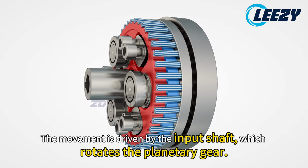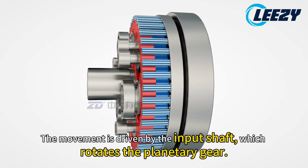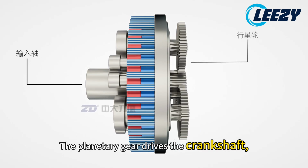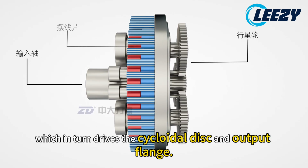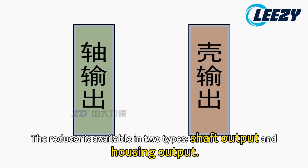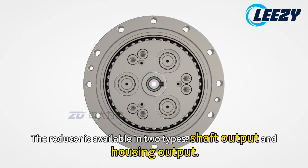The movement is driven by the input shaft, which rotates the planetary gear. The planetary gear drives the crankshaft, which in turn drives the cycloidal disc and output flange. The reducer is available in two types, shaft output and housing output.